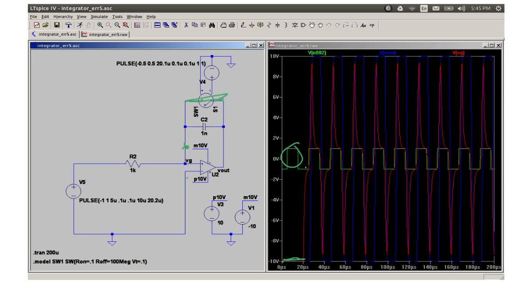When you're switching here, you're sort of forcing it, and it almost follows your waveform. It's not going in the other direction or anything, it's almost following your waveform. You're pumping this node up, and at some point it charges the capacitor and switches it to the way you want it to be, and it sort of follows the waveform at the input. So you can actually use something like this when you want to get a square wave out of a signal that's not a square wave at its input,